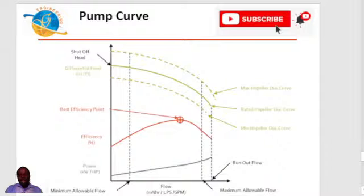So you have to be able to tell yourself, when you are operating further away from the best efficiency point flow rate, the effects on the power requirement for your driver. So you must have selected the right driver for a given operating region.